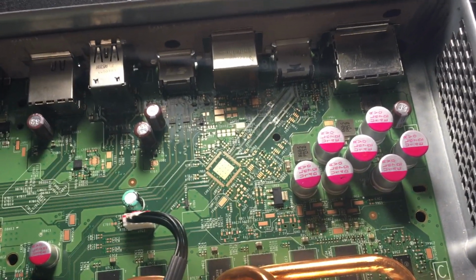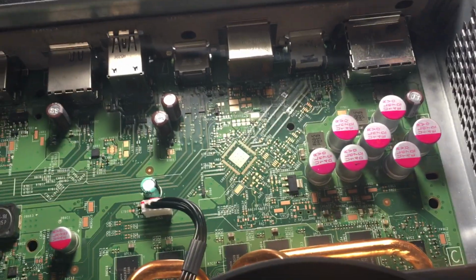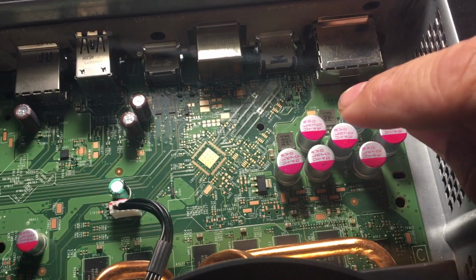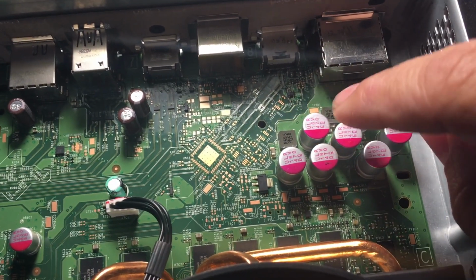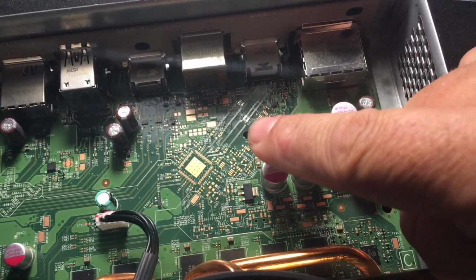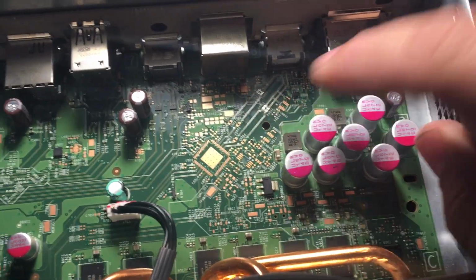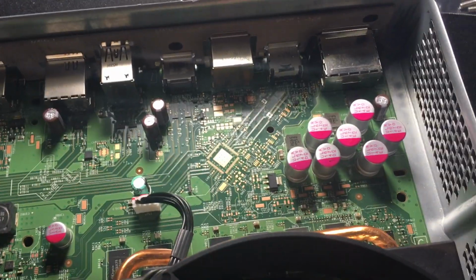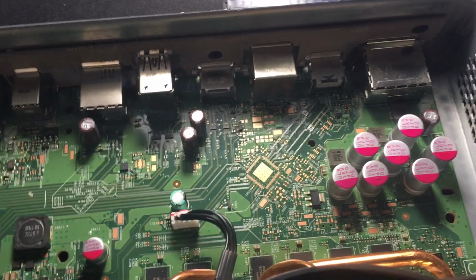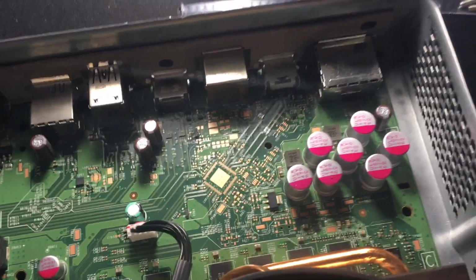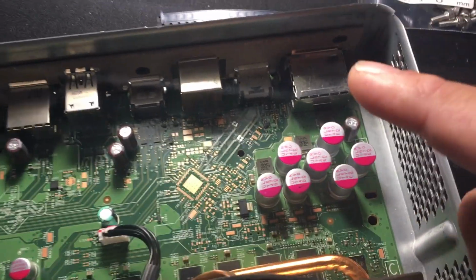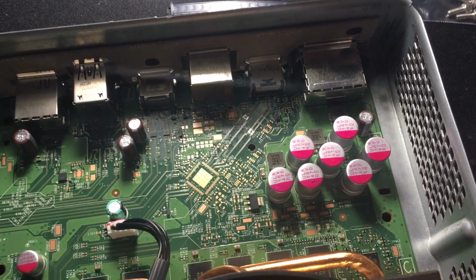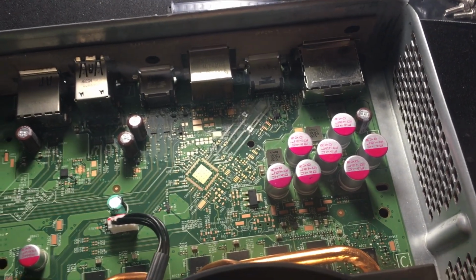Electromagnetic interference is the other thing they do. So they help with any kind of interference either coming out of the Xbox One or coming back in to the signal and messing with the signal. And they're actually straight through connections, so you can remove the filters and you'd be fine. The only issue is now you're not protected against electrostatic discharge, and you could potentially ruin some more important parts in the system later on. Anyways, so that said, I removed the filters and all the problems went away basically. The artifacts went away and the video going in and out went away.